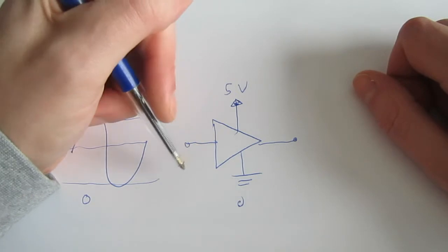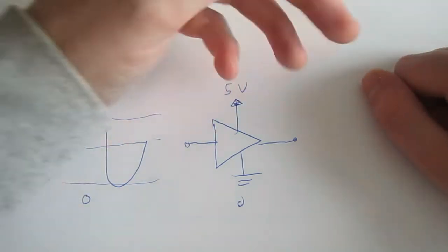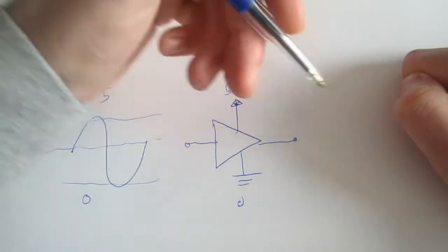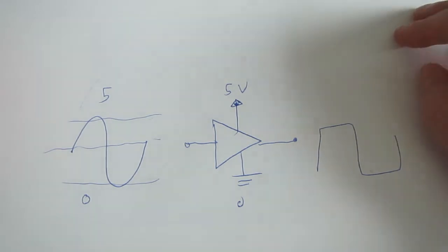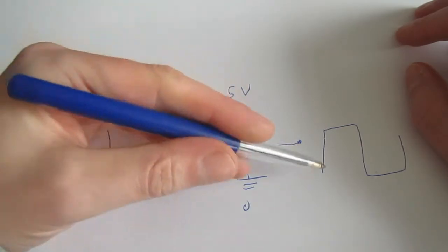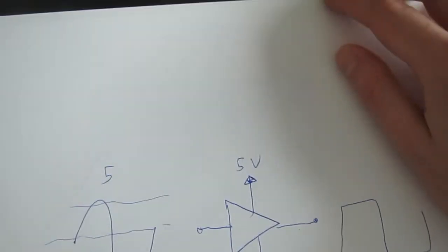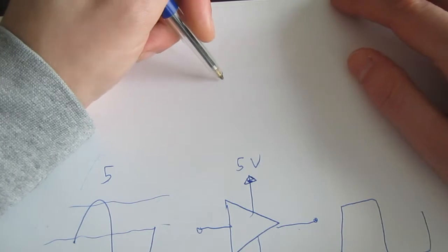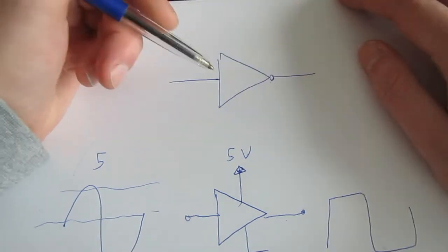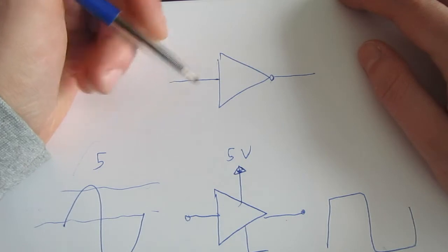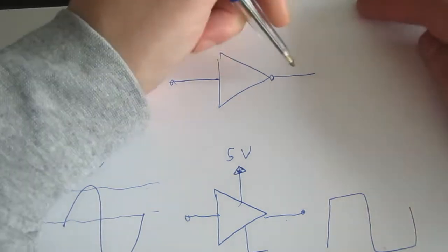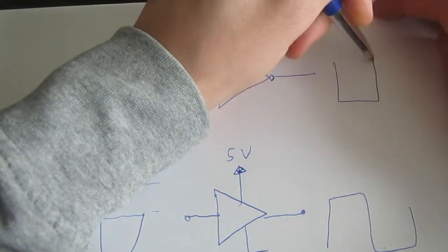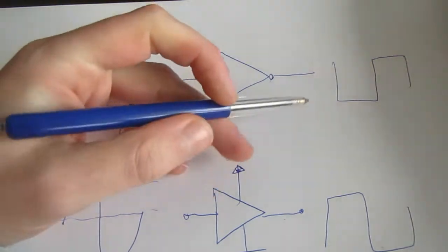And we're gonna set the gain way up high. Now what happens is, essentially, it will turn our sine wave into what people think about when they think about digital electronics, digital circuits, the square wave. Now let's take a digital chip. Let's take an inverter. The 4000 series inverter. There are quite a few of those. Let's put our sine wave in there. Well, what happens? Again, we get a square wave, except this time it's inverted.